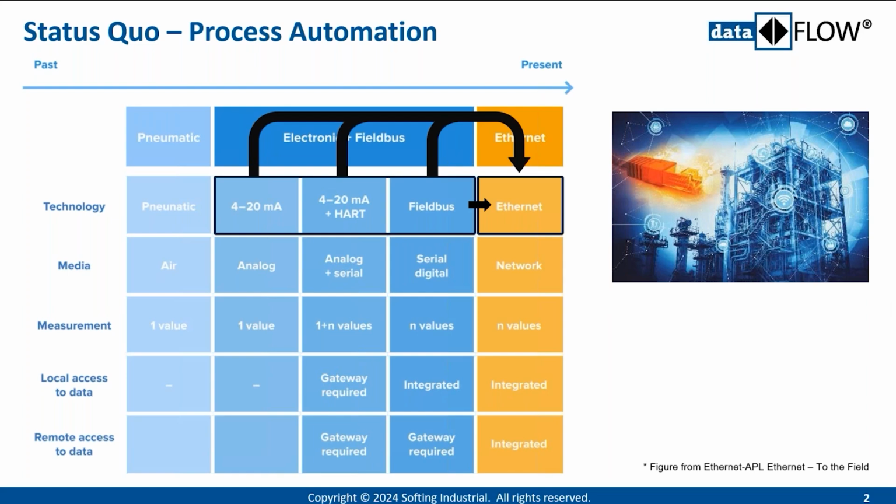So one reason is we want to have the speed, we want to have the digital signals. The other thing we are seeing today is that even with the Fieldbus, we still require a gateway. And one of the reasons why Fieldbus technology and PROFIBUS PA were a little bit tricky to introduce is that it makes things much more complicated. Because at the end of the day, you still have a different network topology, you have different speeds, you have to adjust to that. So you need experts for Ethernet Profinet, but also experts in PROFIBUS PA.